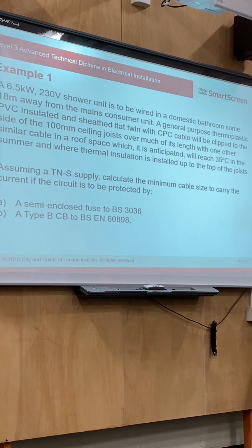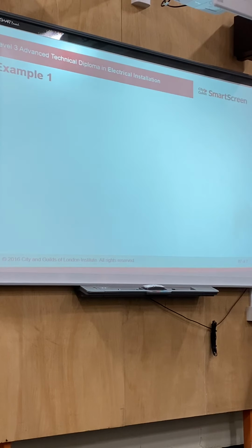What's the minimum depth of this cable being installed in? The technical line nowadays, depending on where it's run. Okay, if you look in the special locations, for some of the special locations, it can be anything from half a metre onwards down. Okay, if the soil's likely to be turned over a lot, it has to be buried deeper. For any general place that you're burying cables, it's any sufficient depth that it won't be uncovered easily. Okay.